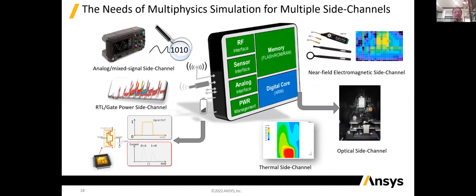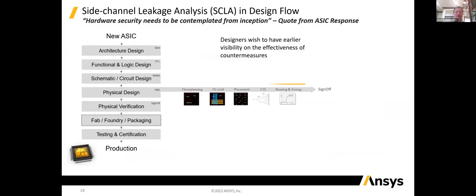So this is exactly a multi-physics problem that we are very happy to look at as a security problem, because every phenomenon needs a new kind of multi-physics simulation: analog mixed-signal design for the screaming channel, RTL gate-level power simulation, thermal side channel simulation, optical side channel simulation, near-field electromagnetic emission. It is also a multi-physics problem that has to be solved quickly, because the equation sequence can be 1 million.